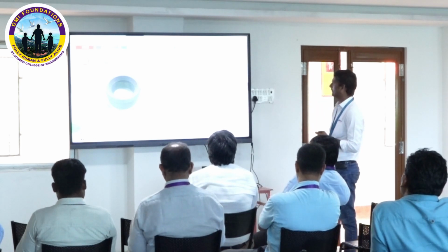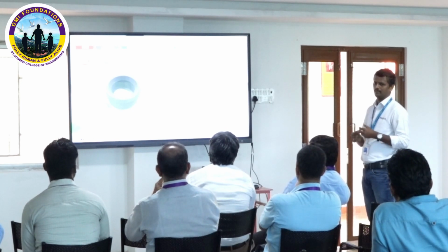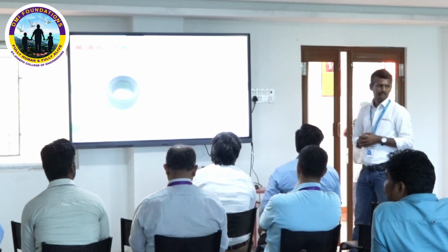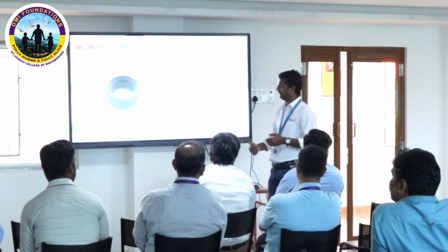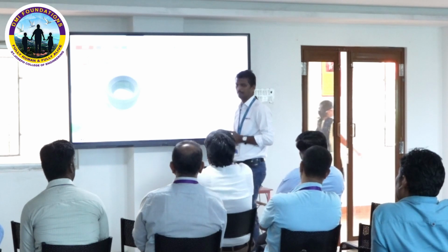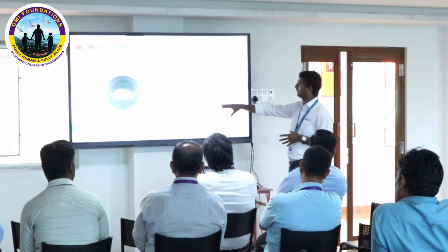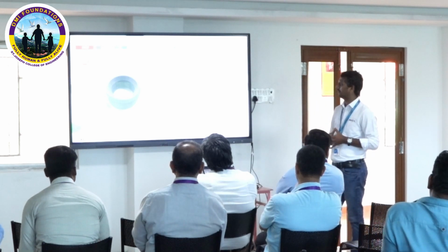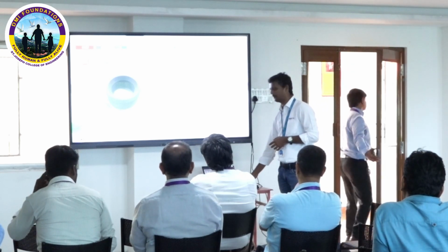And this one is a regenerator component. Here, from the design aspect itself, we can create the porosity. Rather than porosity coming as a defect, we are generating the porosity in the design and building it. And 67% porosity, which is very critical, is achieved here. You can see the inner diameter is around 72 mm, the outer diameter is around 108 mm, and the height is 48 mm. This is also again a proof of concept part.